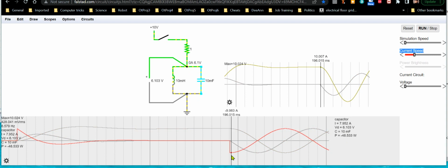But basically, like I said, at the very instant we flip that, you see the capacitor, because this is the current through the capacitor, you can see it highlighted there, actually starts out like you would expect in a way, because now it has this high current source from the inductor feeding it basically. You can see the direction of the current, where it stands right now anyway.